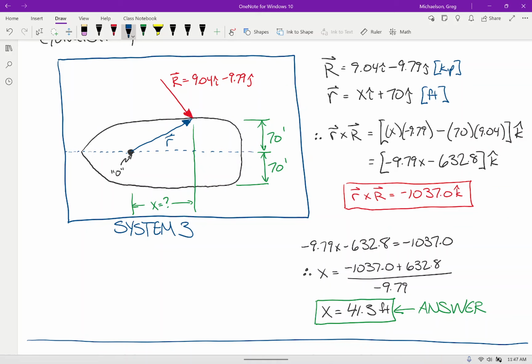So I propose that if we got that 1 boat out there and pushed it right there, it would be doing the same job as all 4 of those boats together. Why? Because this vector has the same sum of forces as all those other boats, and putting it right here contributes the same moment as all of those other forces. Does that make sense? Yes.